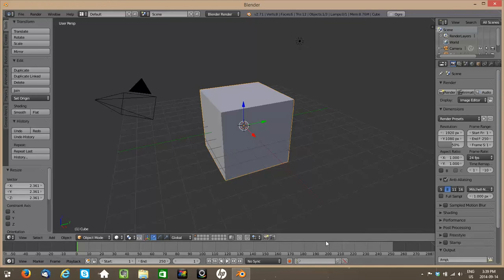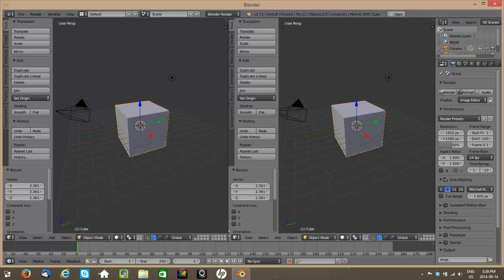The first thing we'd like to do is split our screen so that we have 2 useful work areas. We right-click the border region at the bottom of the screen we want to split, and we left-click on Split Area. Then we get to choose how big or small we want to make our new areas. So we'll roughly cut it in half like this. And we now have 2 displays that are roughly in the same mode. Right? We've split the screen, we've created 2 working areas.